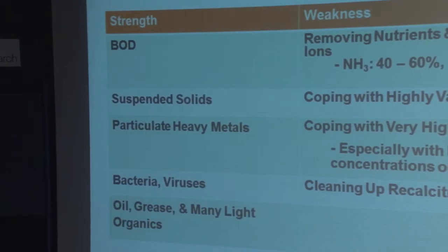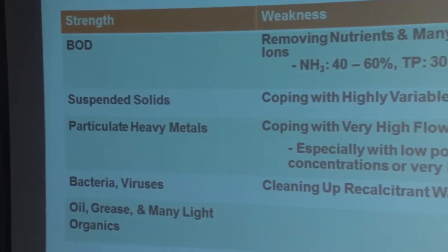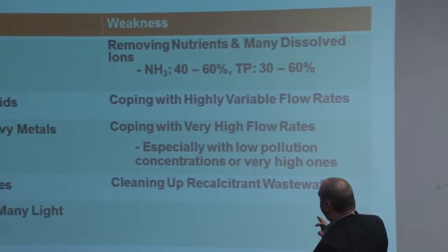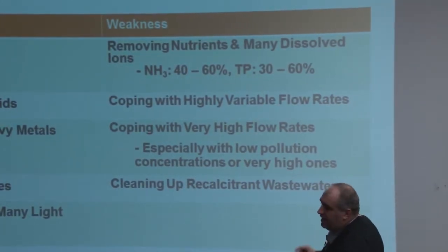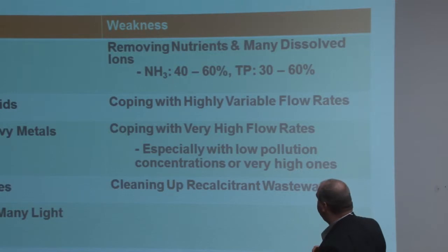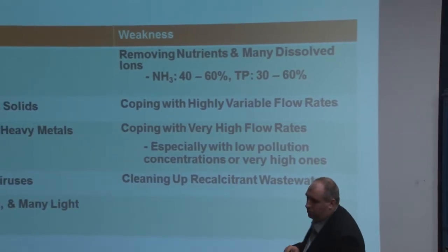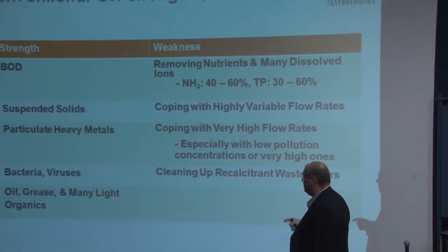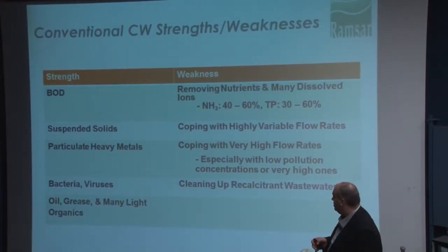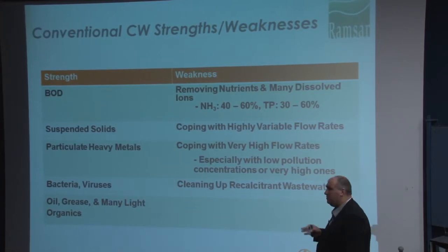Their weaknesses have to do with their ability to remove nutrients and many dissolved ions, coping with highly variable flow rates, and coping with very high flow rates, especially if those high flow rates are associated with a more dilute or lower concentration contaminant load. And then they have difficulty cleaning up recalcitrant wastewaters.